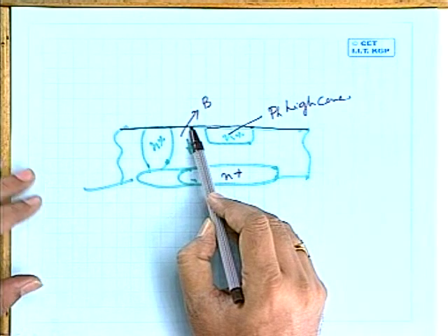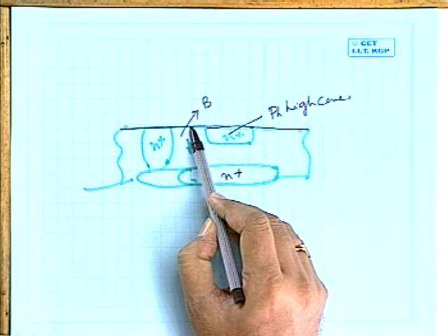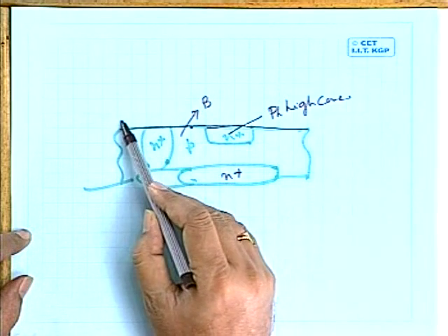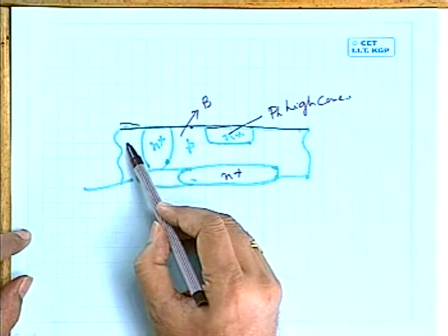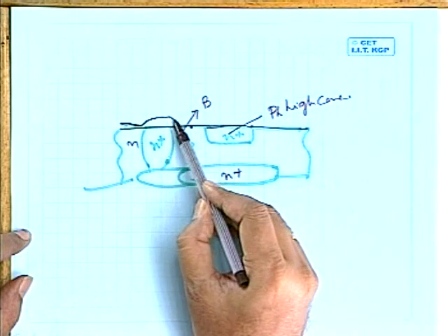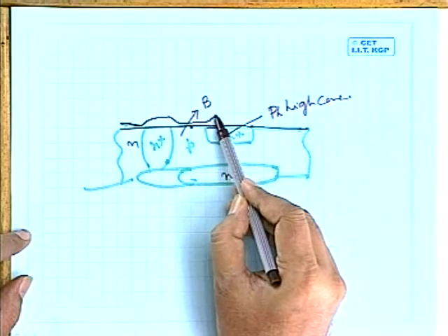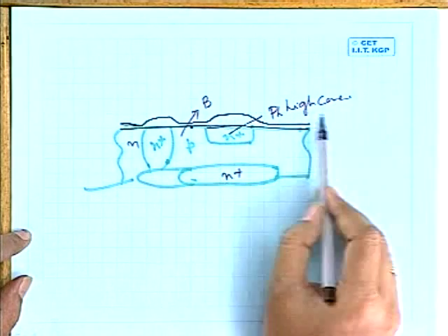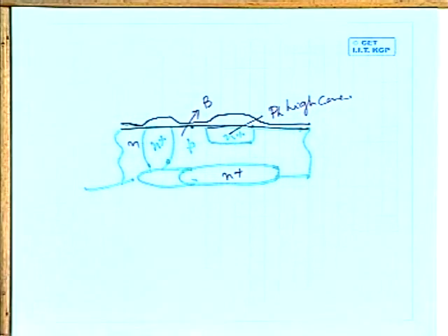So as a result, at the same temperature and same time, if you grow silicon dioxide, the silicon dioxide here will be small, and this is N. Here it will be small, here it will be a little bit more, then again here it is small, then here it is a little bit more, then again here it is small, like this. Then at the surface you are not going to have a uniform thickness of silicon dioxide. So this is really a problem.